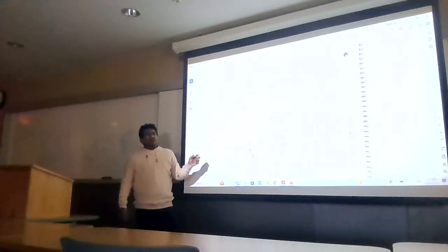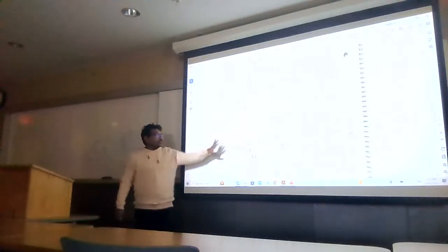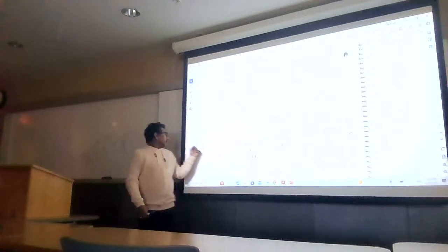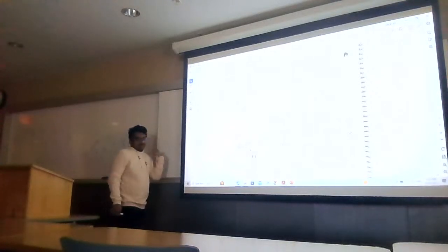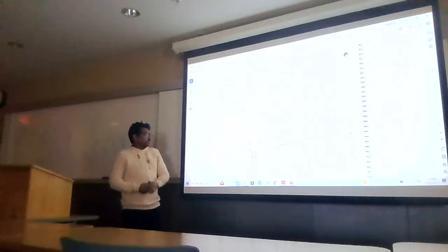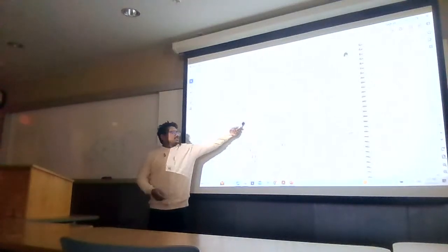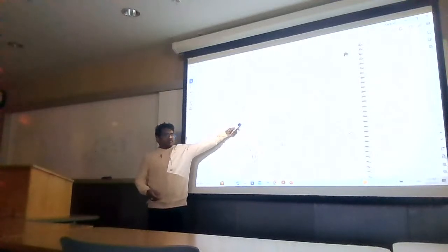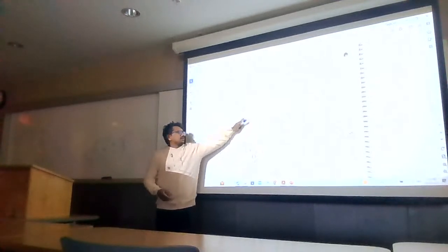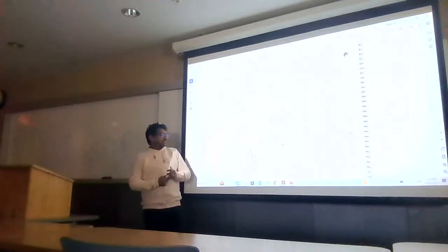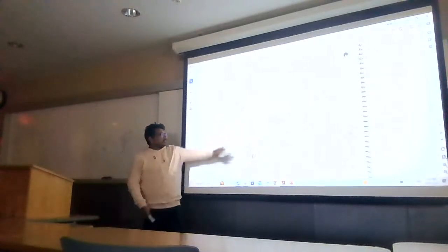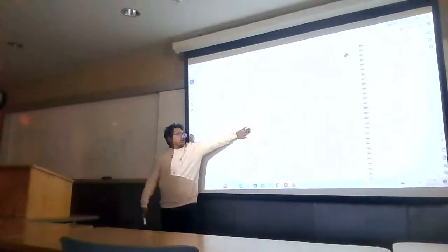And in interview, they will definitely ask some question, let's say here you see the resistance, then I replace it with a transistor. I also can replace it with a diode connected device. This is a diode connected device. The gate and drain are connected. It is known as a diode connected device. And there is also some small signal analysis, let's just assume this diode connected device.